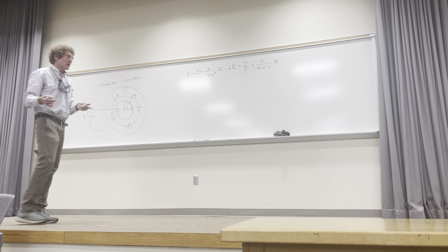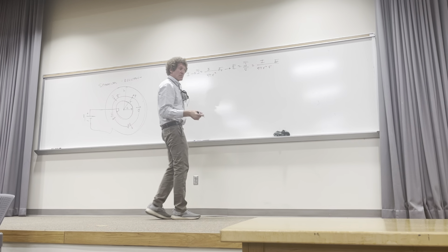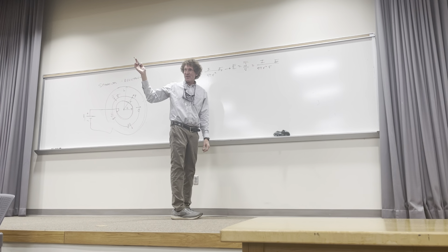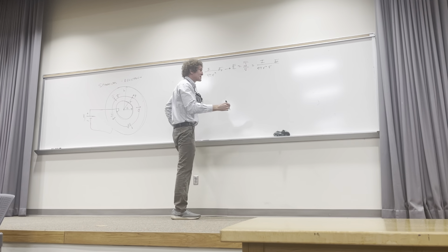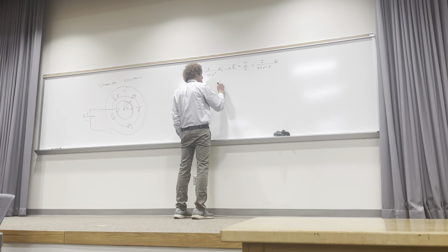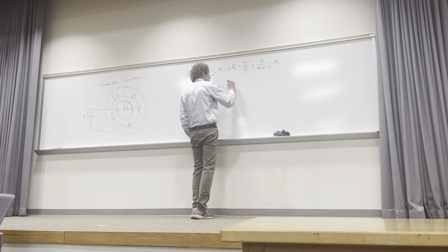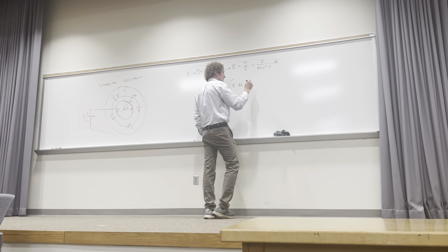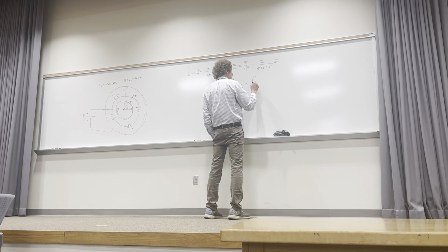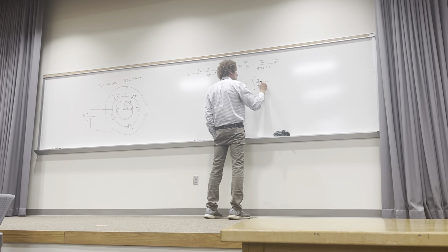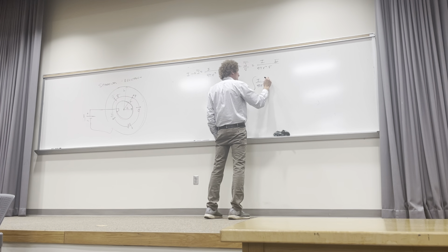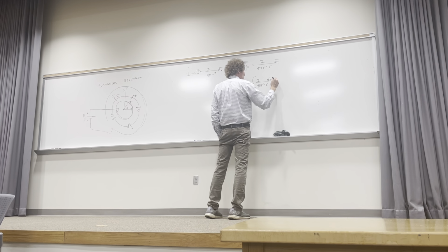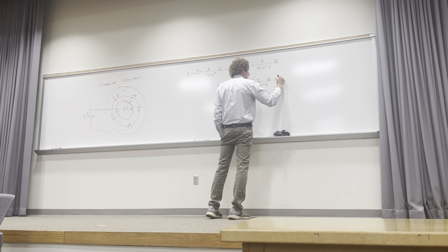Voltage. How do I get voltage? Remember, I know it's going to be positive. Isn't that right? That's the reason I don't worry about that. So I know the voltage is going to be equal to the integral of E dot dl, and that's equal to the integral of what? I over 4 pi R squared sigma a_R, and then dl in this case would just be dr a_R.